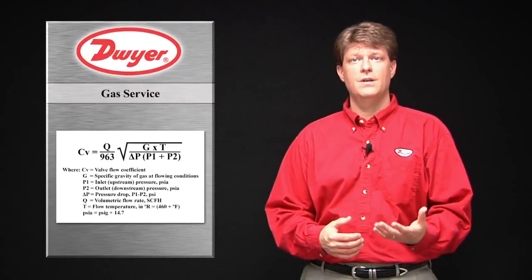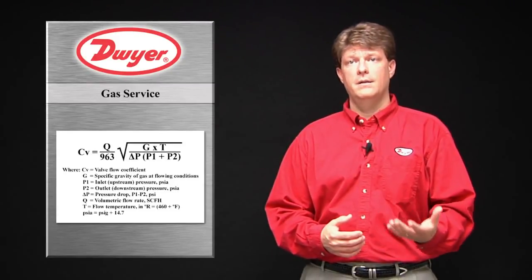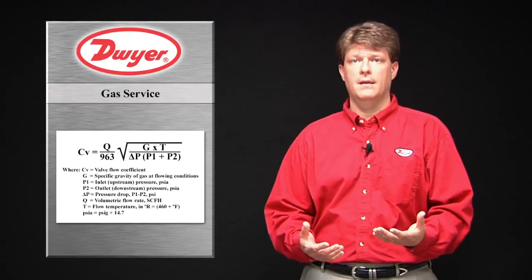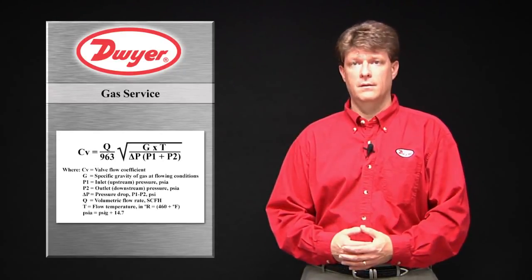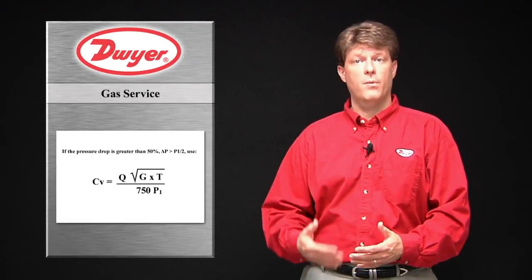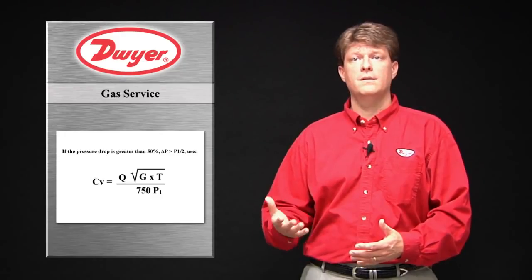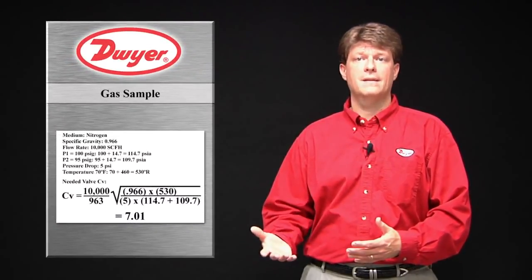For gas, use the equation shown, with CV dependent upon upstream pressure, downstream pressure, pressure drop taken, volumetric flow rate needed, temperature, and specific gravity. If taking greater than 50% of the upstream pressure for pressure drop, use the shown simplified equation. Here's an example calculation for a gas application.